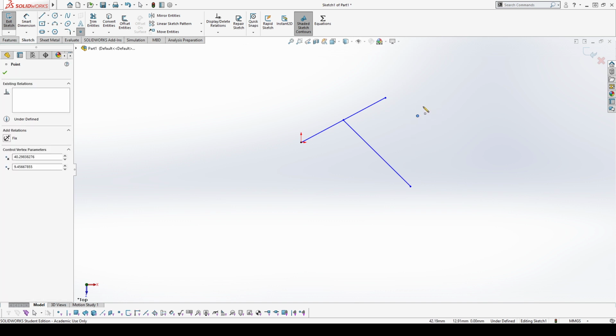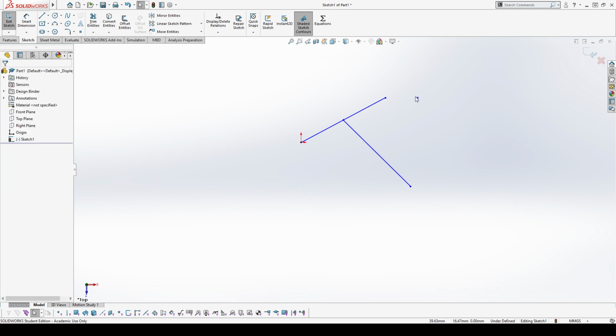The only relations that you really have between two points, so I just dropped in a point there and this other one, or actually you have a couple of different options. So horizontal, vertical, and coincident. Coincident is the main one there. If I wanted these two points to be at the exact same XYZ coordinate, that's what I do for coincident. But also, one of the handy things is that you can make them horizontal to each other. So without actually having to go in and draw in construction geometry, you can make these two horizontal to each other. In general, you have to have a little bit of judgment here. It would be helpful to actually have that construction geometry in there.